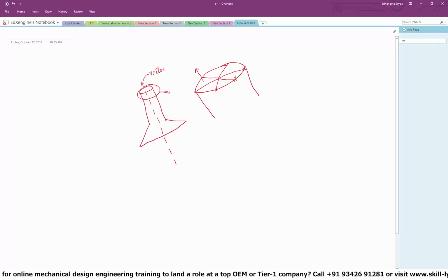So how does the arc thing work? When I select 3 points, I can construct 2 vectors. Let me demonstrate that. I'm going to take up these 3 points and draw them separately like this. The spacing between the points has been exaggerated slightly for clarity. So with 3 points I can create 2 vectors. Let us say this is vector number 1, V1, and this is vector number 2. Now if I take V1 cross V2 and call this vector V3, then the direction of V3 is going to be perpendicular to V1 and V2. That is basically your cross product. So similarly, when I take these 3 points and compute the cross product, I will get a new vector that will have the same direction as the valve axis.